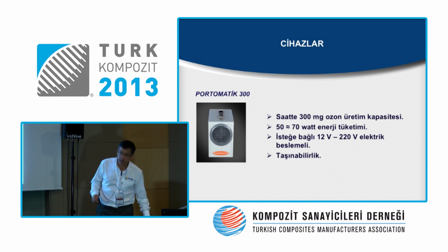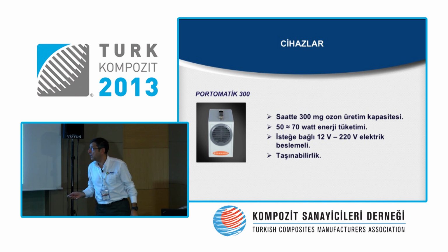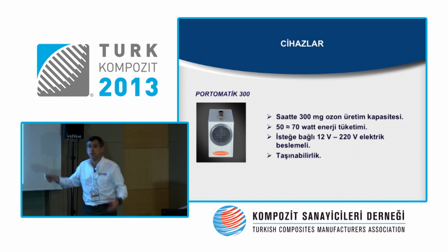What about devices? Based on how much ozone you want to receive, this will vary. These are samples. These are portable machines. They're mobile. They're usually used for households, schools, hotels, and other environments where they need to be moved from time to time. These produce approximately 300 milligrams of ozone per hour. We use them for car washes, etc. In Istanbul, we have approximately 50 of these machines being used right now, serving these purposes. They work on 12 volts or 220 volts.